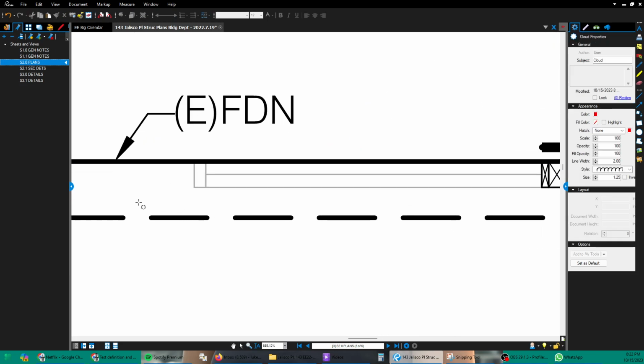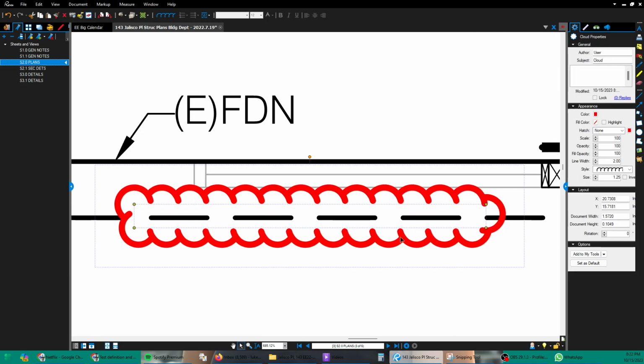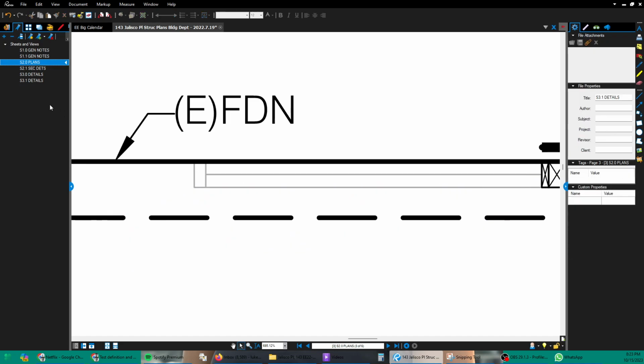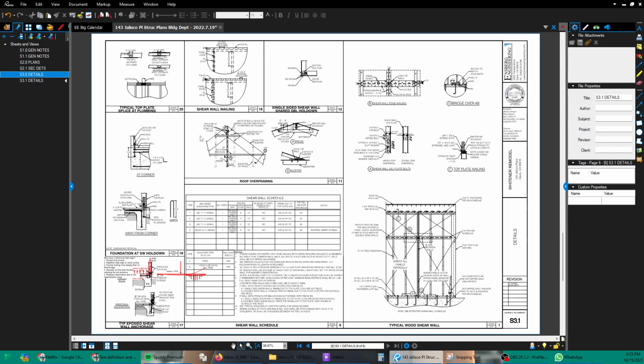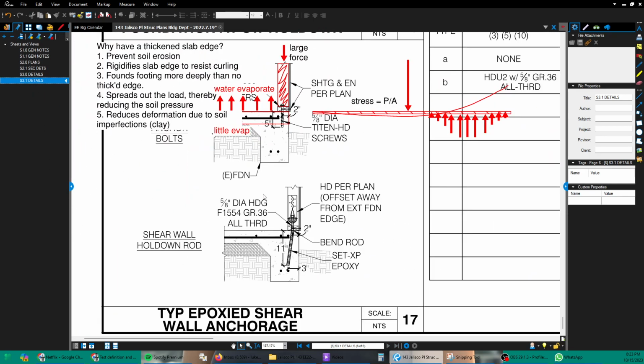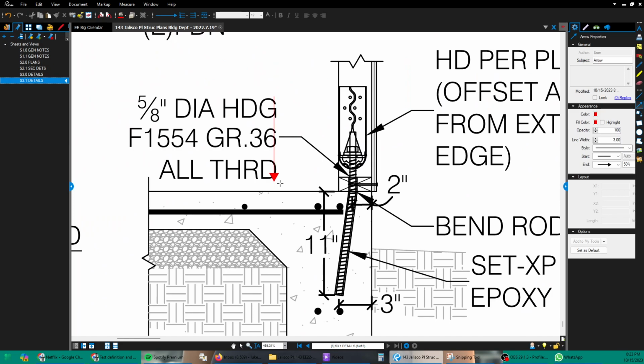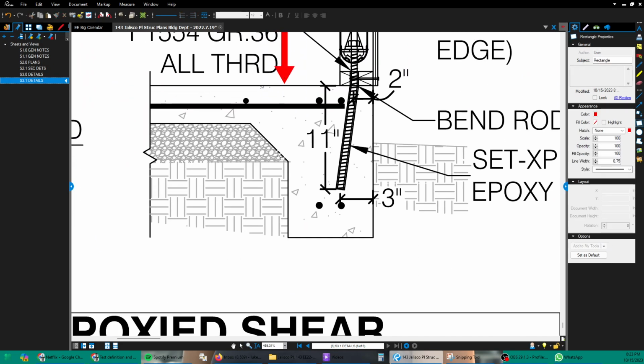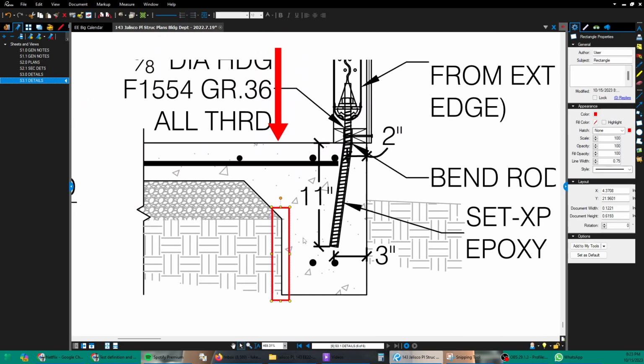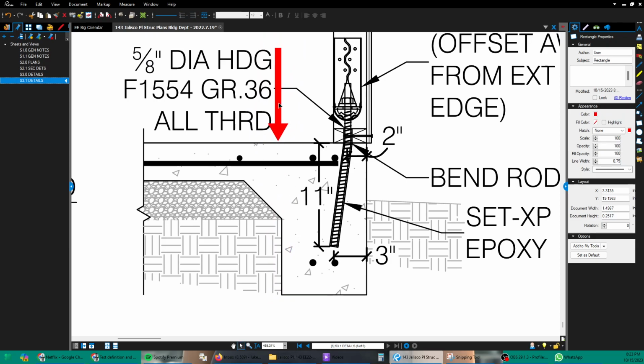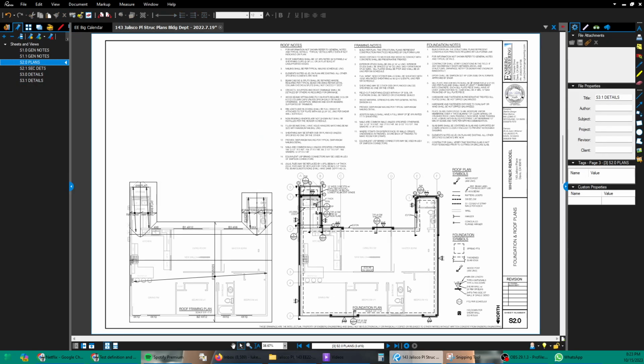Okay, so in this case, what is hiding the inside thickened slab edge from our view? Why is it hidden? 3, 2, 1. You're correct. It's hidden because it's under the slab surface. Right, so when our eye looks down, I cannot see this line firsthand. It's inferred as being underneath the slab. It is there, but it's beyond my view, so it's represented with a dashed line.